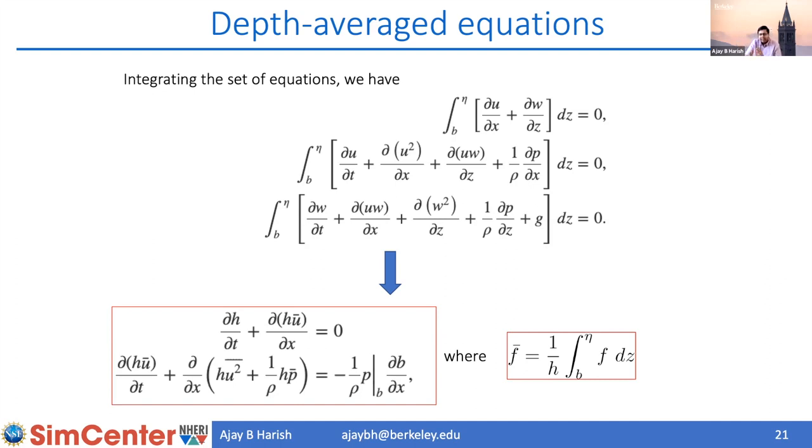So essentially what we have is these depth-averaged equations, where we have the rate of change of the height of the water column, and the spatial change, the gradient of this H times U bar quantity as well, right? So I just want you to have a look and understand that these are the equations we are starting with. That is what GeoClaw is solving for us.